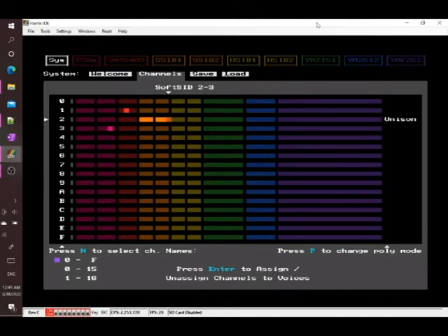You can combine voices from different chips, too, for really interesting timbral combinations. The other 2 polyphony modes, by contrast, work well if you set all of the voices to the same waveform. Pressing P here changes the polyphony mode to polyphony steal. This means that you now have 6-voice polyphony, and if a 7th note is played, it shuts off or steals the first note. One more press of the P key gets you polyphony limit mode.